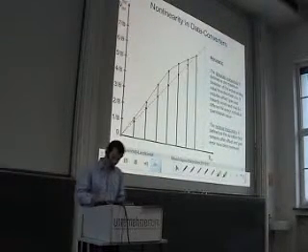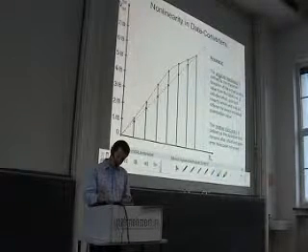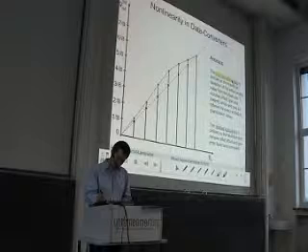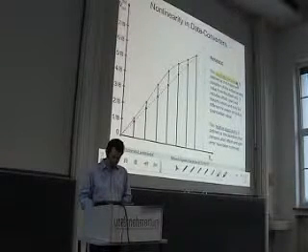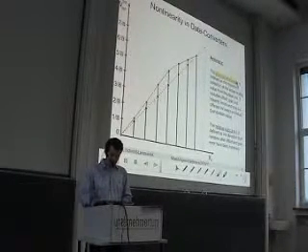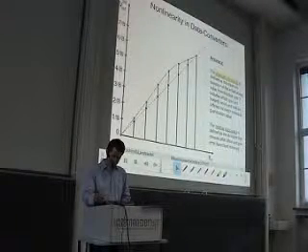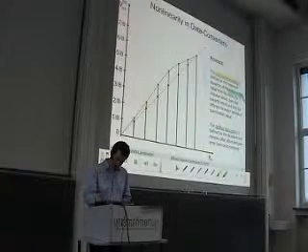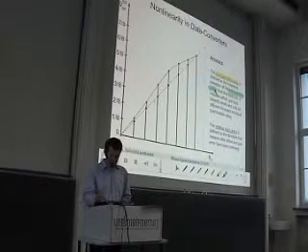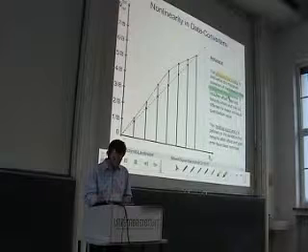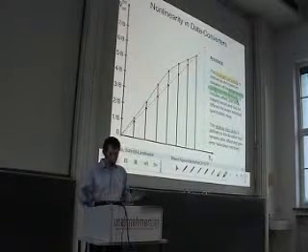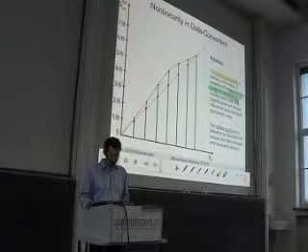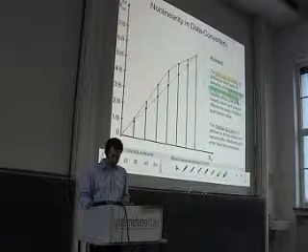So the first one is the absolute inaccuracy, and let's read the definition together. It is defined as the maximum deviation of the actual analog value from the ideal one. So as nothing is cancelled out, it includes of course the offset and the gain error.